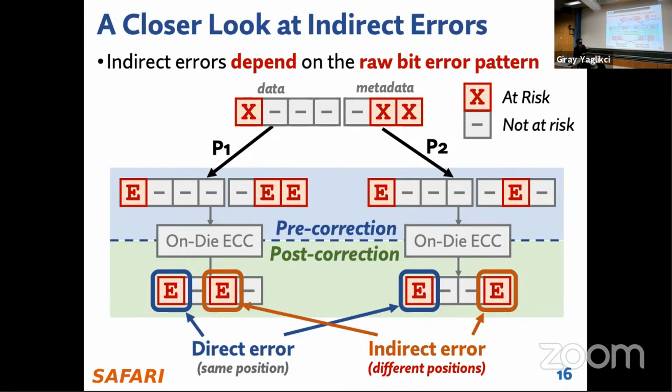But this is what I was saying, typically in these memory devices, we use this type of encoding because, for example, imagine that you're going to do a read operation. In the common case, you won't have an error, right? Well, assuming you're operating at relatively low error rates. So then all you need to do is just return these to the IO pins. There's no data transformation necessary. So you save on energy, you save on latency, and it's just generally desirable. But I mean, you don't need to do it this way. So this is an assumption that we're making. Does that clarify?